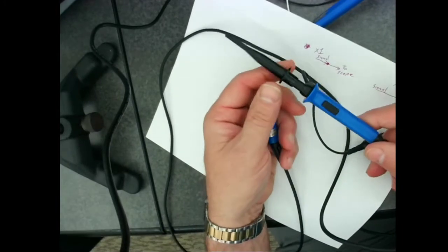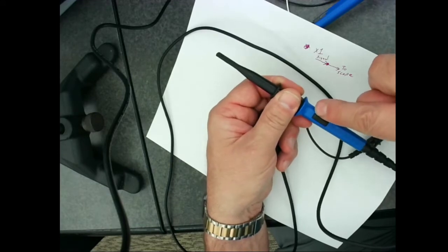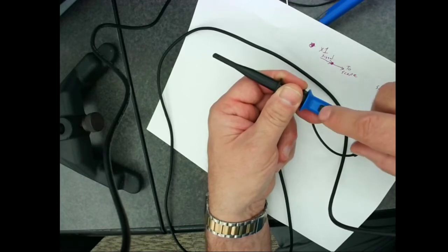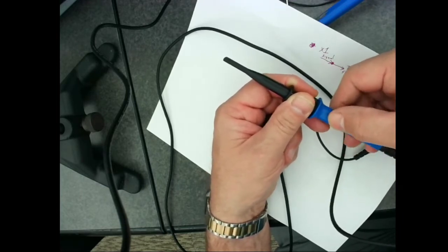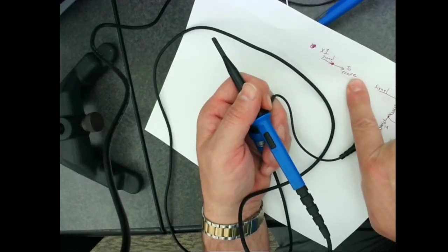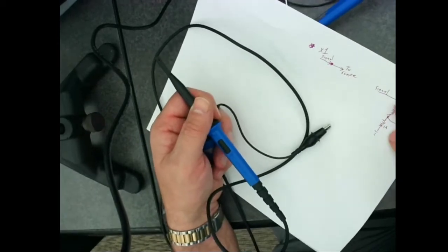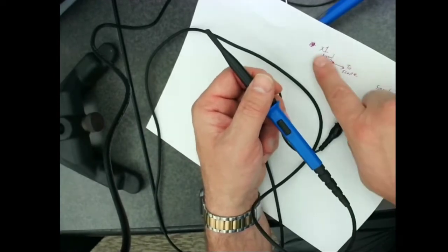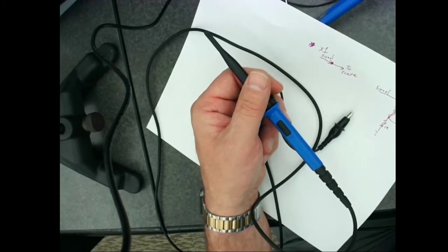Now, this particular probe actually has a switch on it. If you read here, you probably can't see this in the video, but it says 1 times or 10 times. So depending on where you switch it, it'll be either a 1 times, which is just a direct feed to the scope, or a 10 times, which runs it through this voltage divider. So whenever possible, I recommend that you use the 1 times, especially if your input signals are noisy